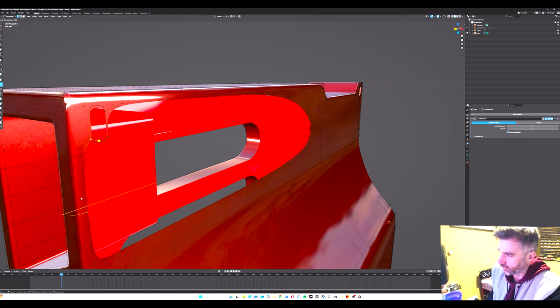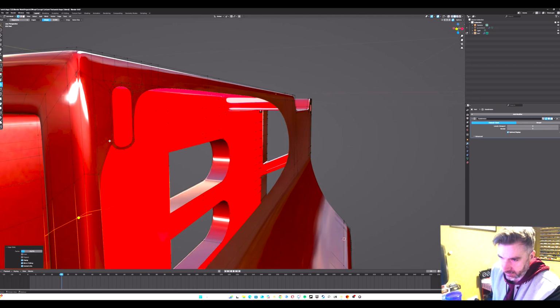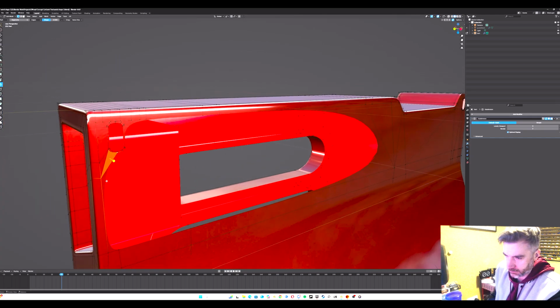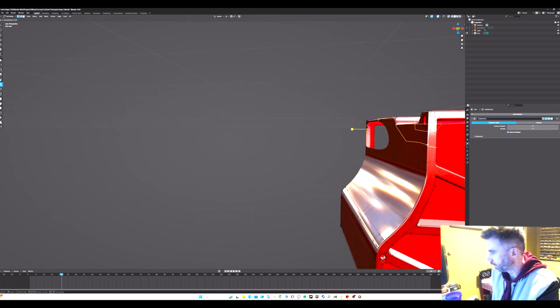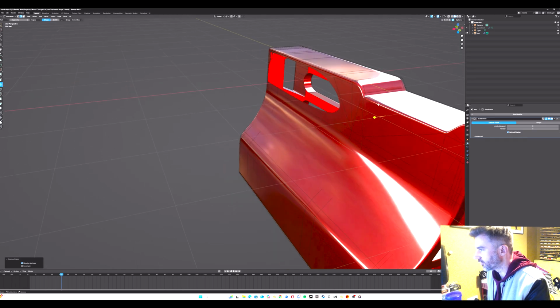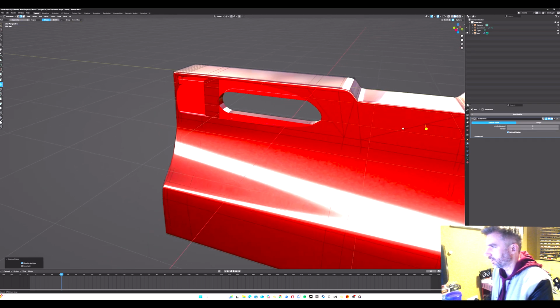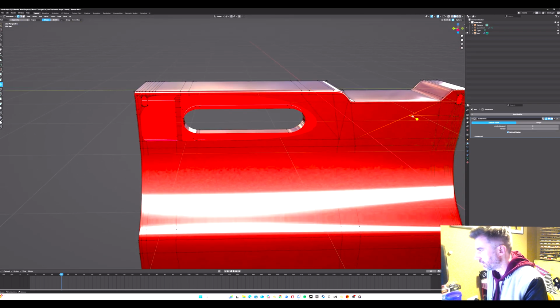And I think it would be beneficial to put another cut in there, which you can slide up, and we'll deal with that on the other side in a bit. And we can actually just keep attaching to that one point for that half. Try and put a cut in there, things get crazy, but what we can do is put a cut in here and move it to there, then dissolve this edge. Just check where our actual line is. Dissolve this edge and then select all of these and dissolve that edge because we don't have all this craziness going on. And then we're going to run our cut all the way across.